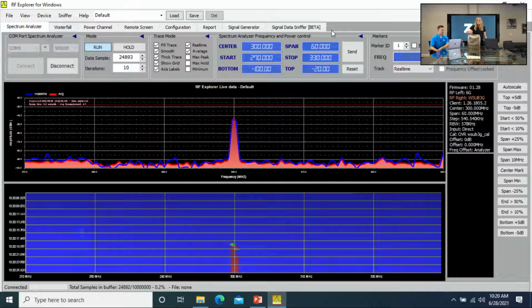So I'm going to stick this into our shielded box, and what you're going to see is that start to go down, and once it's fully zipped, that's going to go all the way down to the noise floor. In goes the generator. As you see, it's already lowering. We are going to get the best shield once it's fully enclosed. And there you go. A full live look at shielding interference.